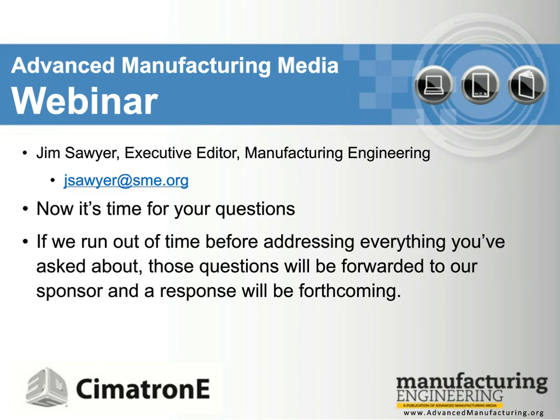Well, if the electrode box is selected, then that enables that parameter to work. In fact, that's how I used to have my template. I would have the template set with the electrode machining checked, but you can leave the values out. And then when you're ready to put the overburn in, you can do it as I showed with the electrode edit spark gap.